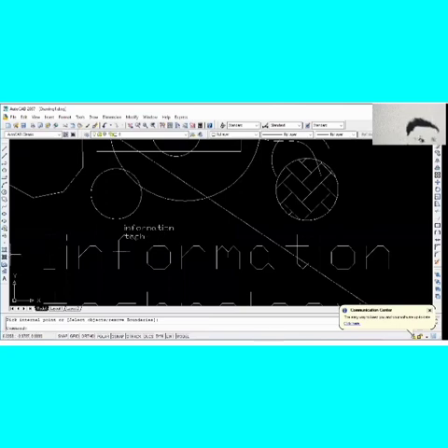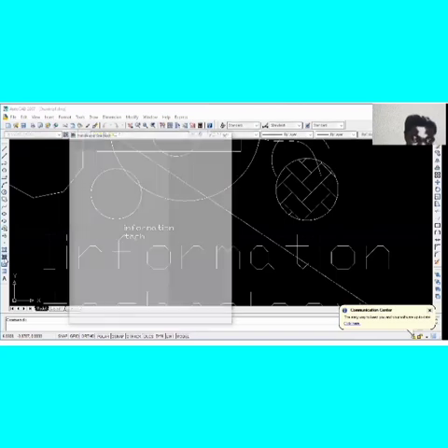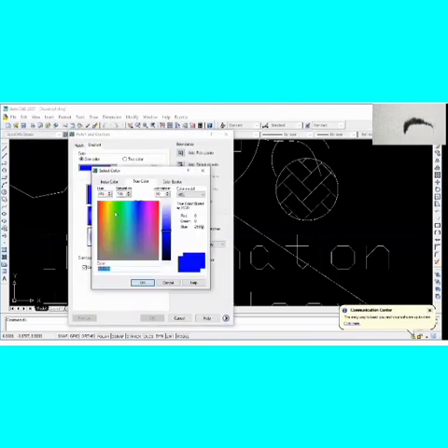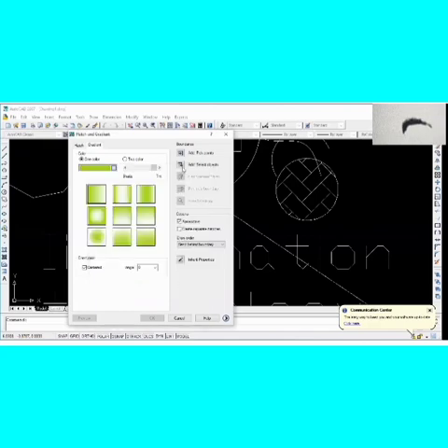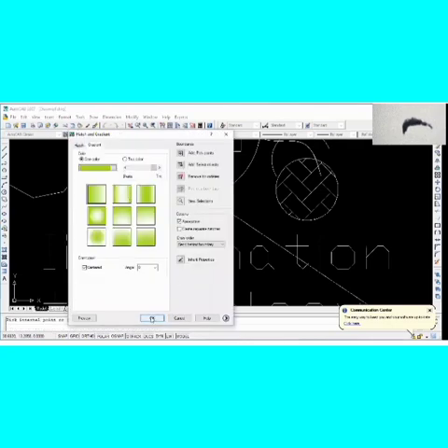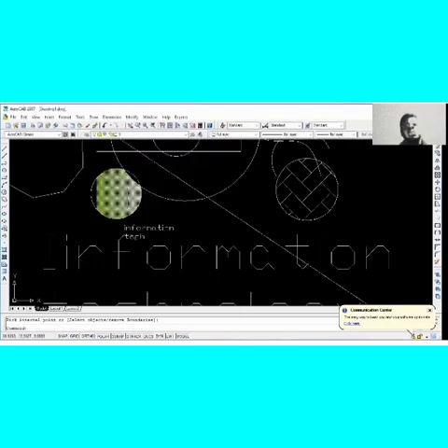Now back to gradient. Your gradient also has ellipses. When you click on it, you can choose the one you like. After choosing it, choose the color you want. Okay. And then now go to add pick point. Come to this place. Let's choose this within this area. And then right click, enter. And then if you are through, click on OK. And that is your gradient. You get it? So that is it about some of the drawing tools that we have.